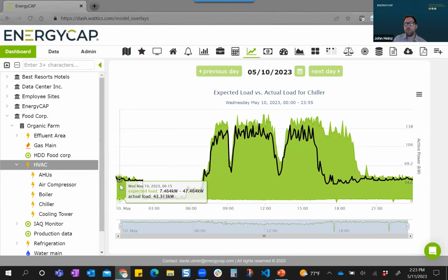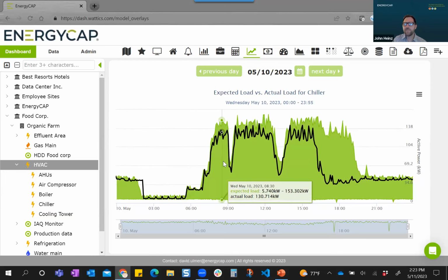So for this HVAC point, it's saying, well, generally we have deep setback during morning hours, and then the system starts to cycle on about 6 in the morning. We have some different time periods where it peaks and then drops off, and then we get some setback at night. You'll notice for this point, what we're actually seeing is the HVAC generally has been turned on a little bit later in the evening, and maybe more recently, the organization said, well, let's start doing setback a little bit closer to end of workday instead of a few hours after, and see if we can get some savings.